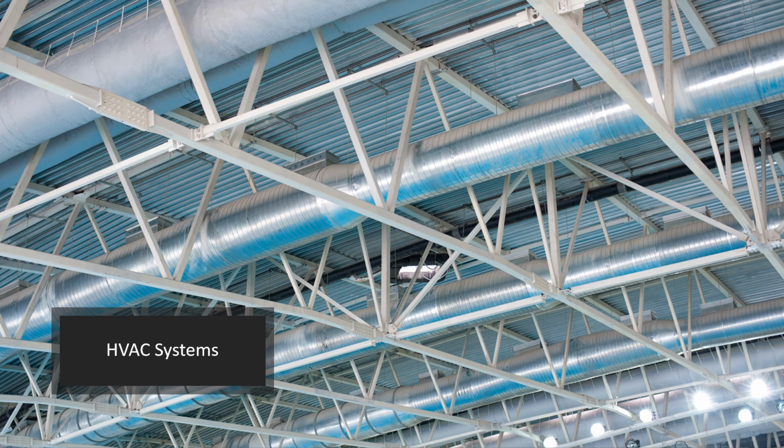And smart thermostats allow for automatic adjustments to the HVAC settings, optimizing energy consumption while maintaining comfort. Now, your HVAC system and sports venues must operate quietly to avoid disturbing events or causing discomfort to spectators and players. Sound dampening materials, vibration isolators, and proper system design can help reduce that noise level. In locker rooms or offices, careful selection of ventilation systems, fan types, and placement can help minimize noise as well.